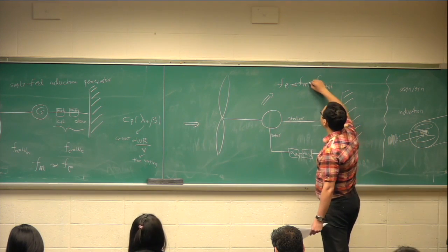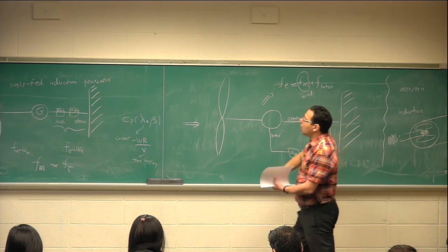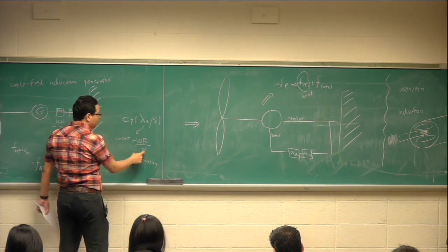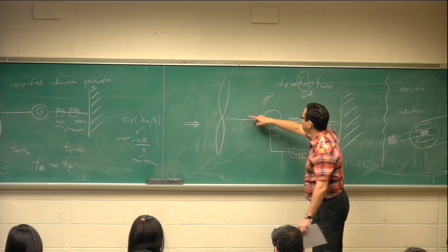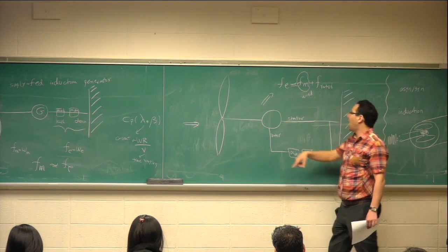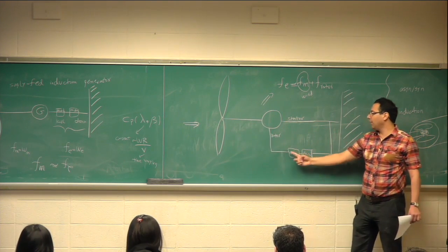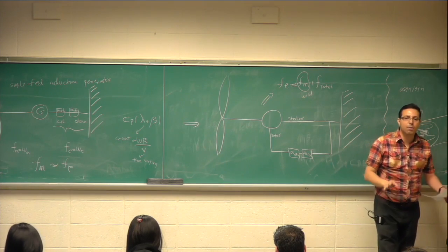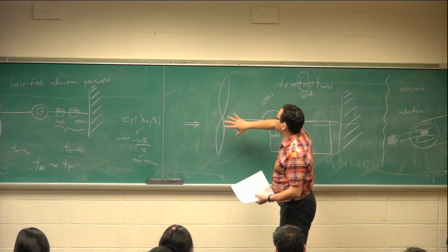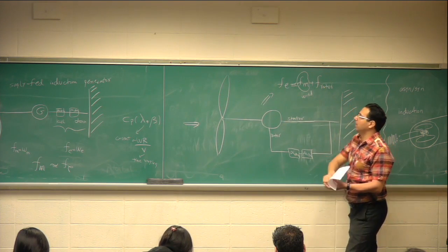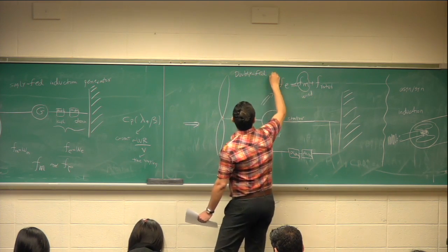And now assume that this comes out of wind. You like to adjust this in real time. Wind is changing. You adjust W in real time. Assume that this is changing in real time because of wind. How can I get 60 hertz here? In real time, I measure wind. I control the frequency for rotor. So this is the most commonly used type of wind turbine in practice. Doubly fed in the whole system, doubly fed induction generator. So this is called doubly fed induction generator.